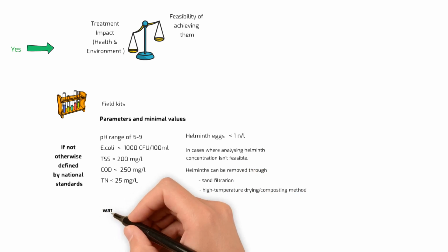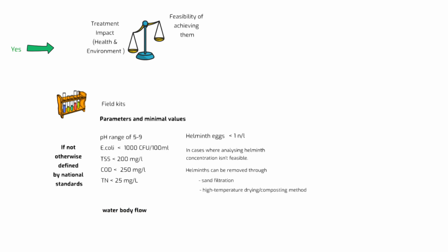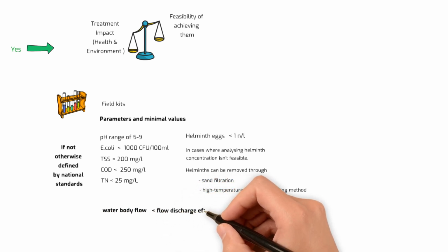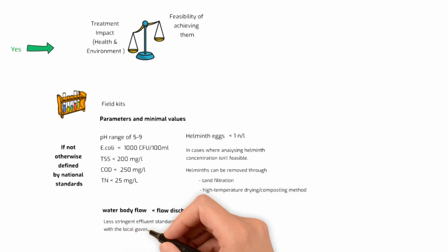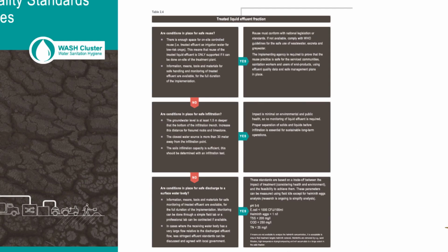When the receiving water body's flow significantly exceeds the flow of discharged effluent, less stringent effluent standards can be negotiated and agreed upon with the local government. Navigating these questions and responses ensures careful and responsible management of treated liquid effluent.